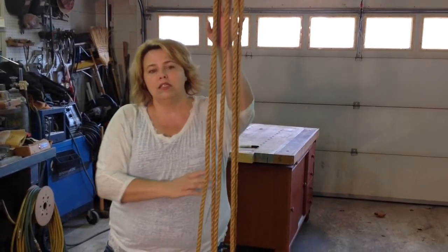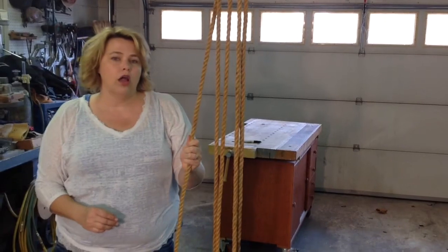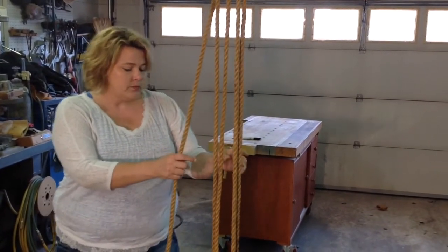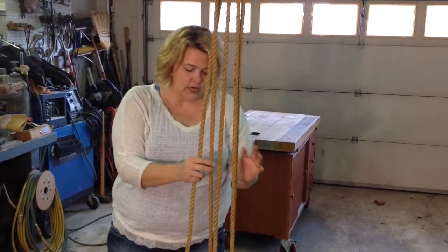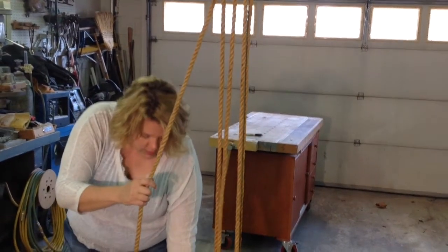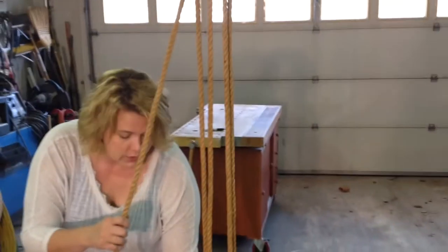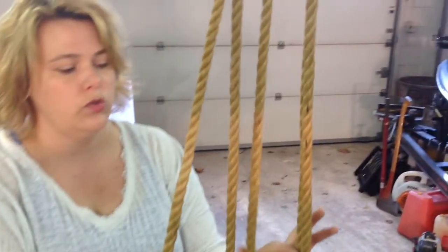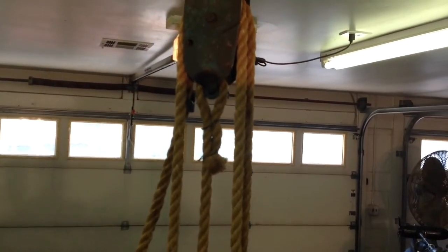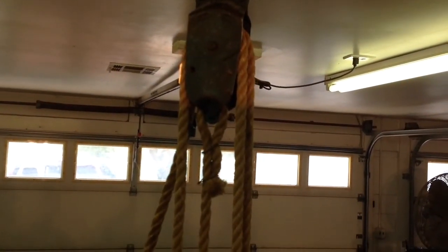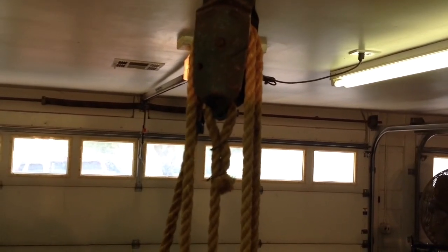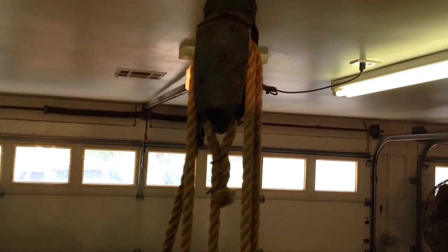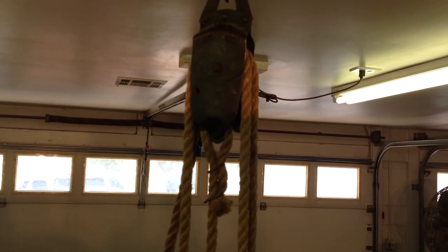But I'm using this as our example to find our ideal mechanical advantage. So this one, like I said, I've got 4 strands supporting this weight. It's a boat anchor down here at the bottom. All right, and I've got 4 strands, as you can tell, 1, 2, 3, 4. This one here is just coming up over and changing the direction. So my ideal mechanical advantage for this pulley is 4.